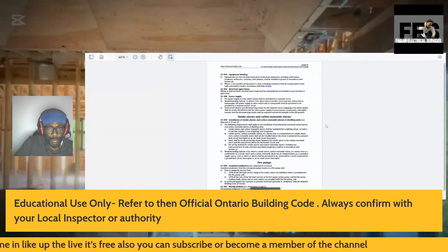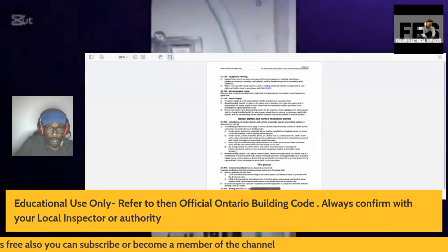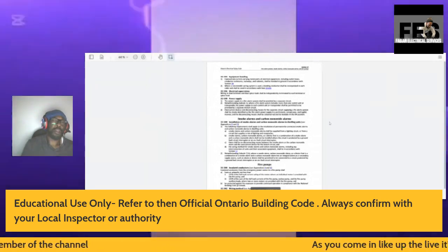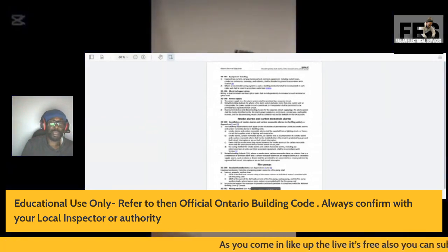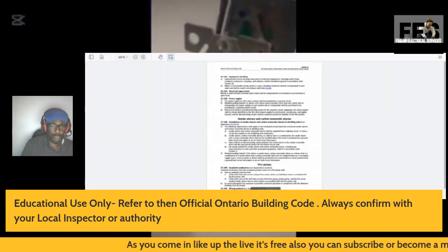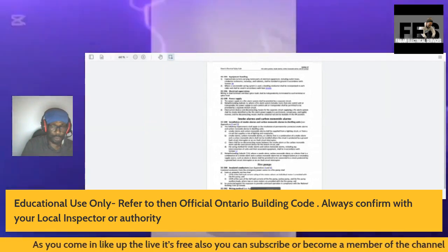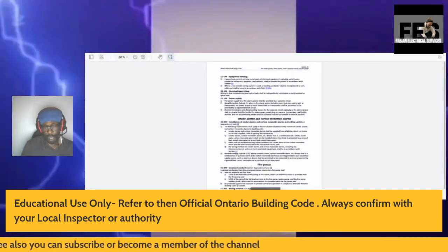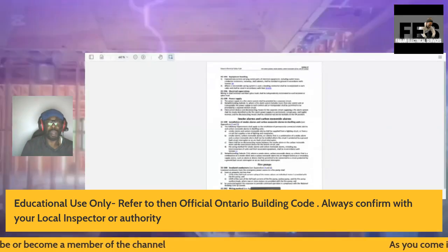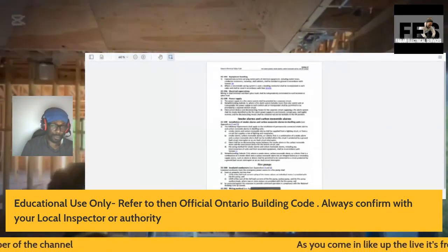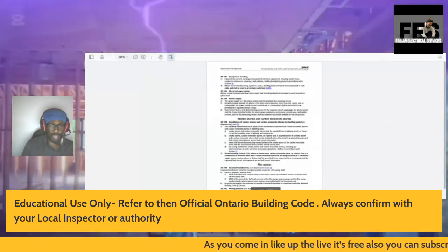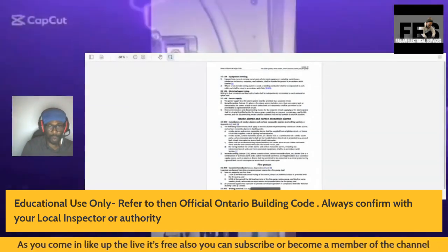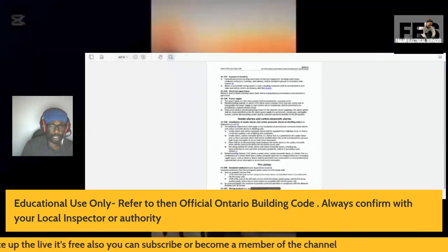Okay, so we're now at smoke alarms and carbon monoxide alarms. Smoke alarms are very important. It's life safety. It helps you get out of the home in time once functioning properly, meaning that you have to have your backup battery in place. Make sure your backup battery is always working, just in case you do lose power from the main power coming into the smoke detector itself.